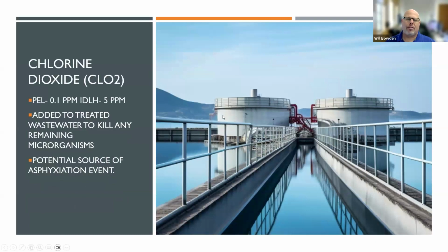Next one that we would like to discuss is chlorine dioxide, or ClO2, as some in the industry will call it as another term. The personal exposure limit for that one is 0.1 ppm. IDLH is 5 ppm.